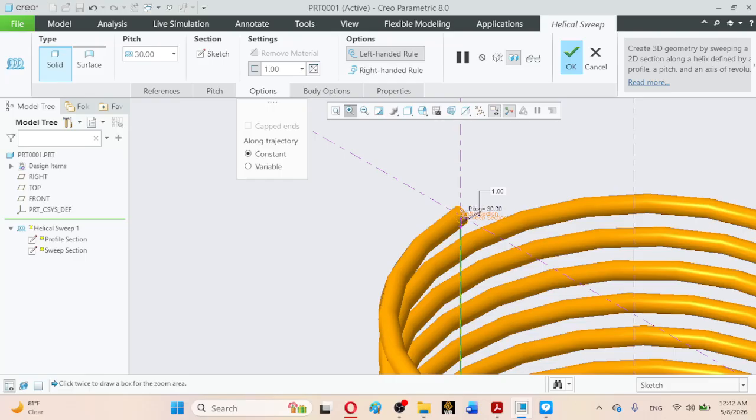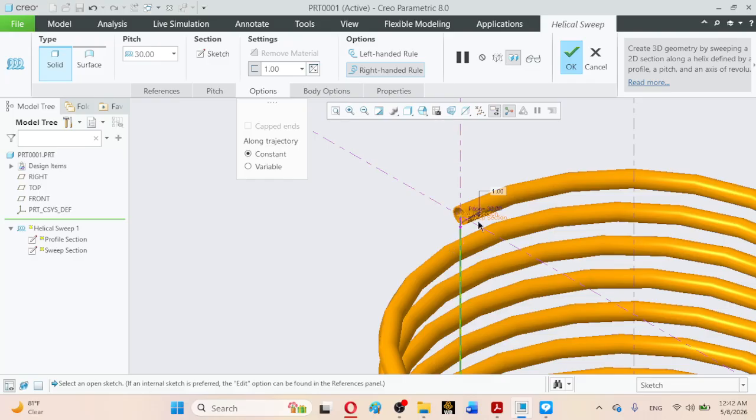So if the top helix is opposing the tips of the fingers of the right hand, then it is a left-handed helix. And if it is ending in the direction of the curling of the fingers, or in the direction of the tips, then it is a right-handed helix.